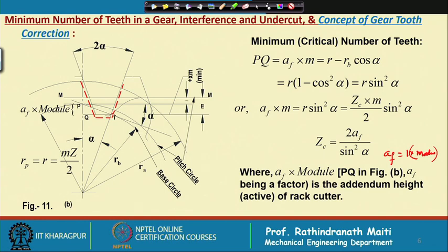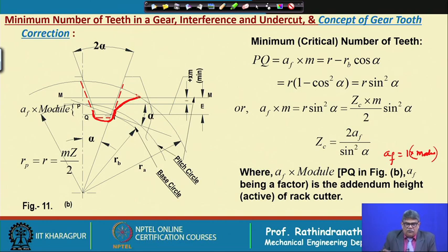So, this red line which we have considered still has the addendum equal to 1, but as it has come down, the tooth profile will be something like this. And if we notice, not only is there an extra cut here, but also this available involute profile is above the base circle, not from the point of the base circle.